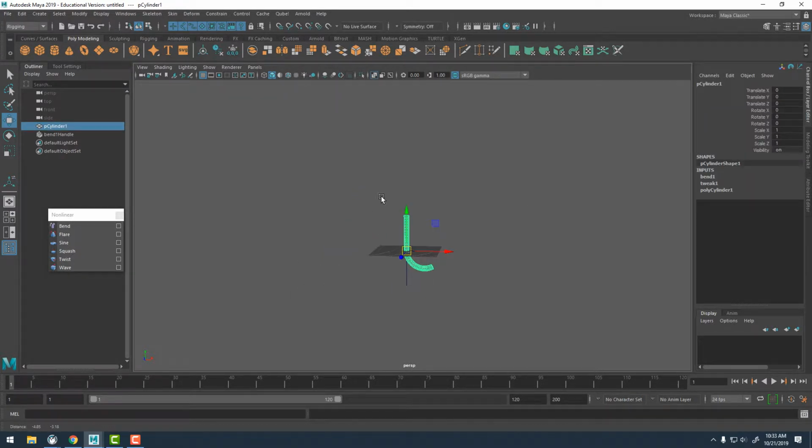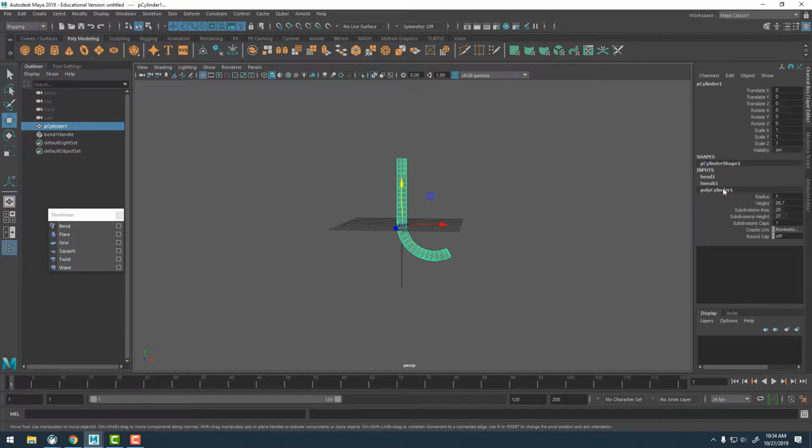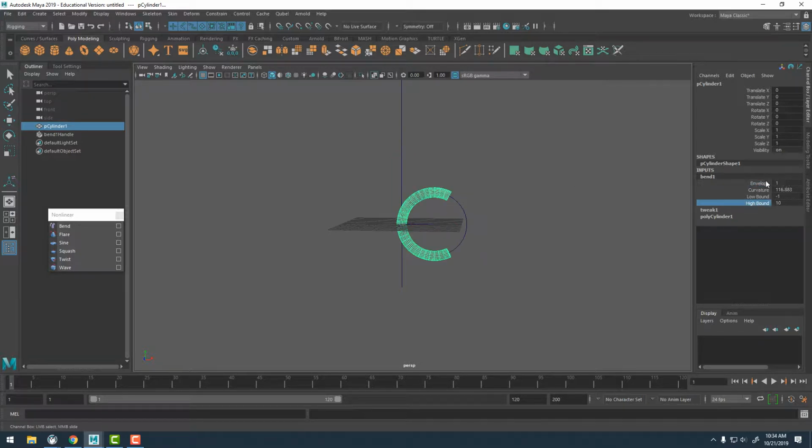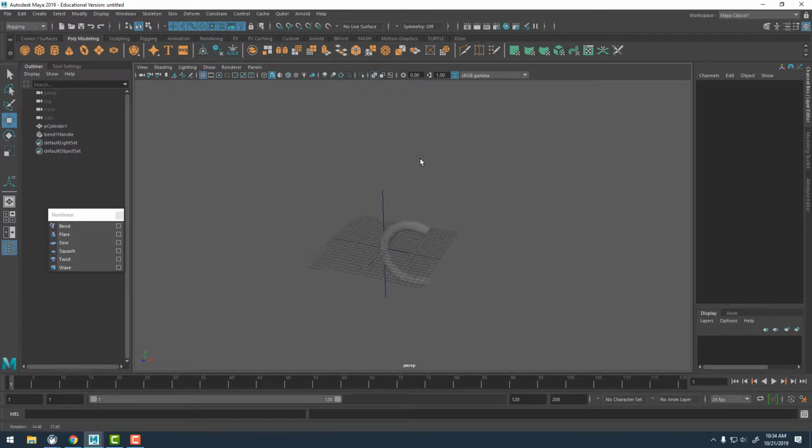Just like our other deformer there, the lattice cage, you can animate your geometry along this curve. So if I push this down, it's going to align along with the shape of the curve itself. Let me undo that. Is there anything else with this one? I guess we could see the envelope. Let me take that high bound back up to its default. So again, the envelope just dictates the overall influence. So if I take the envelope from 1 down to 0, it'll eventually get rid of any influence this deformer has. And again, that's something we could key and animate.